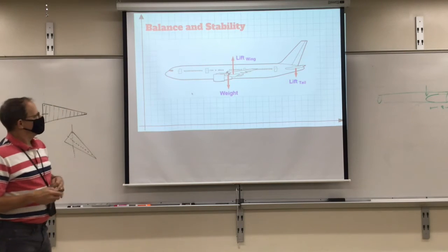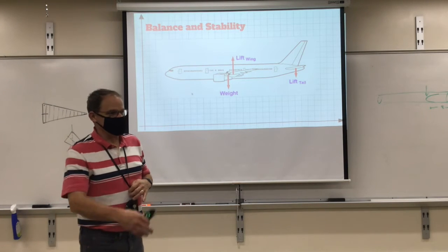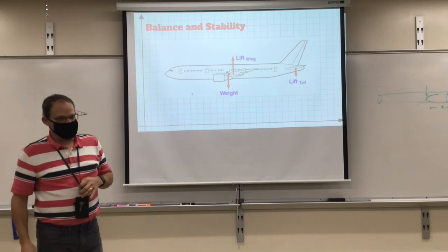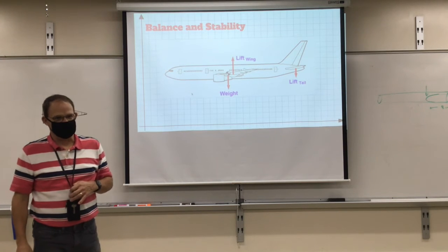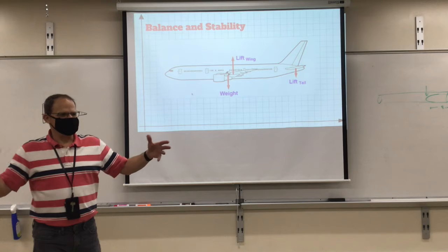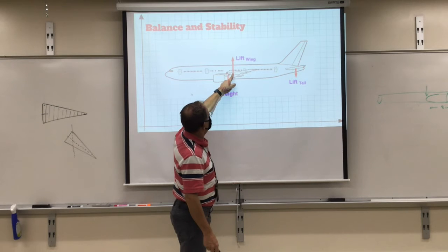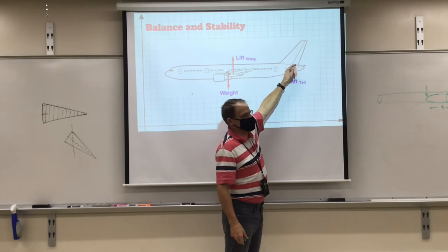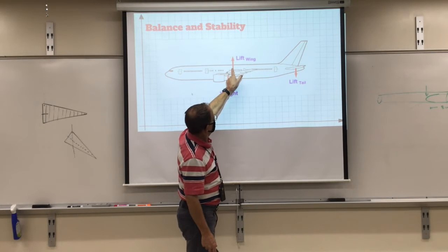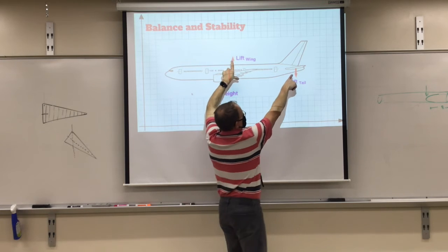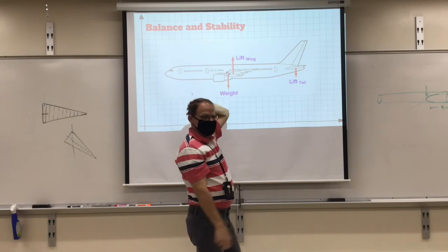So that's about stability. Also, the center of mass of an airplane is very carefully calculated. If you fly a small plane, the pilot will probably say, what do you weigh? You sitting back. What do you weigh? You sit in front. They've got to distribute their weight carefully. On a bigger plane, it sort of averages out, but they also have to carefully load the luggage. But the center of mass needs to be somewhere slightly in front of the lift center, because the back wings actually push down, okay? And if the center of mass was here, that would tend to rotate it downwards, and the back control surfaces apply downwards. It tends to make the nose go up, right?